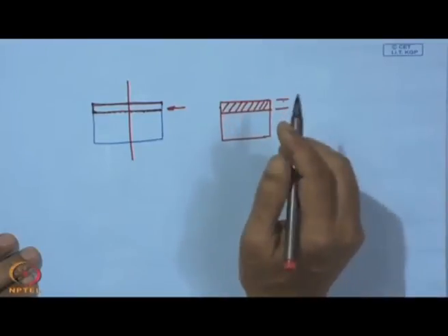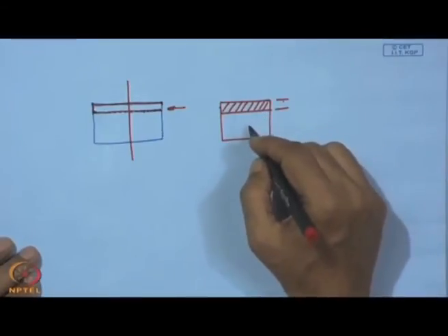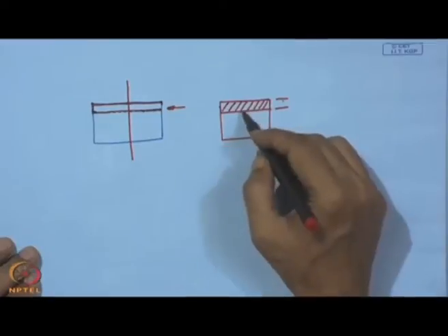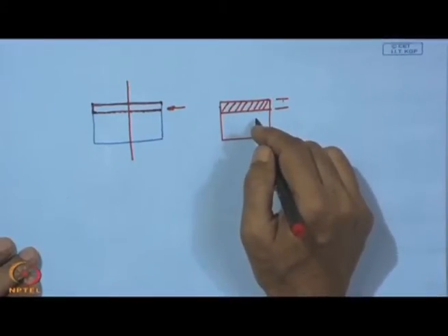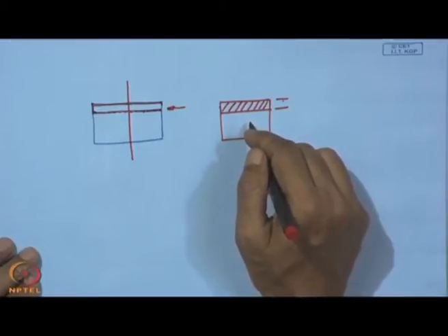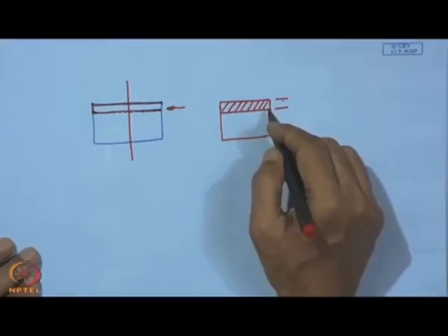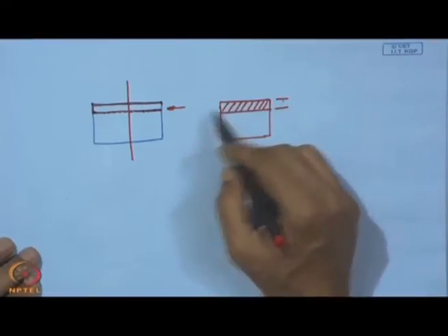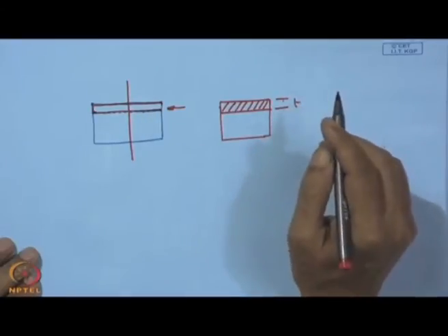and here it is actually a metallograph. So, polishing has to be done with proper care so that edge rounding does not take place. All these things should be handled with adequate care and precision, so that the entire coating bandwidth can be revealed under the microscope. This way one can also find out the thickness of the coating.